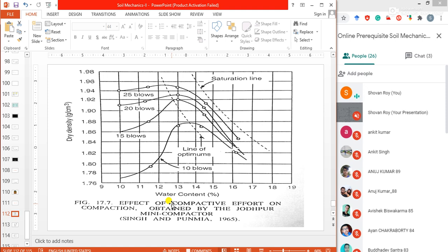This is the first stage. When we perform this rolling or compacting process, at that time we should always check that our soil is compacting properly, and that our soil has the exact amount of water content which I calculated as OMC in the lab.